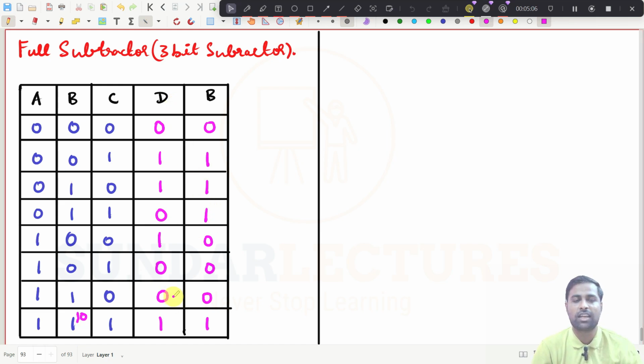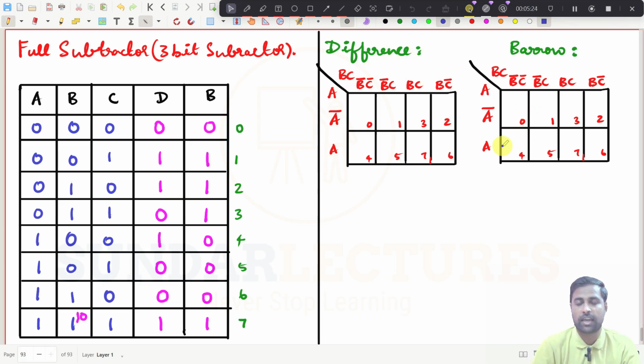So now this is the truth table for the difference, and then this is for the borrow, right? And I will put the K map here. I've just drawn the K maps now. So you put the difference in this K map. So this is 0. For 1 it is 1, for 2 it is 1, for 3 it is 0, and then for 4 it is 1, and then for 5 and 6 it is 0, and for this one it is 1.